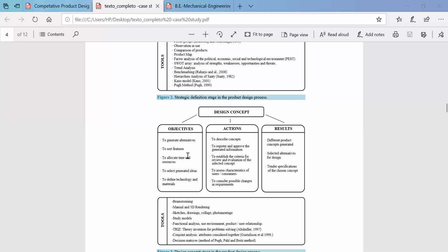Okay, so finally, once this is done, you will define which technologies are needed in order to convert this design into the product, which materials are needed, and which materials are suitable to manufacture this particular product, because every material has its own key properties. You should see which functional properties the product you are manufacturing needs. Based on the functional properties needed, you have to select the material.